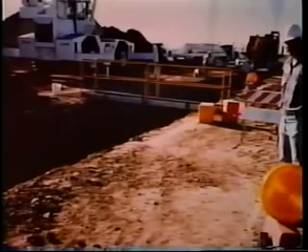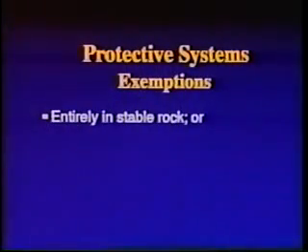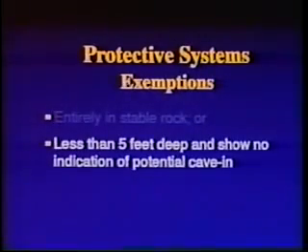Excavation safety requires pre-planning. Let's take a look at some other areas where anticipation of possible hazards can help avoid accidents and injuries. OSHA Standard 29 CFR 1926.652 contains requirements for the protection of employees from cave-ins through the use of protective systems. OSHA requires that each employee in an excavation be protected from cave-ins by a protective system except when excavations are made entirely in stable rock or excavations are less than 5 feet in depth and determined by a competent person to show no indication of potential cave-in.